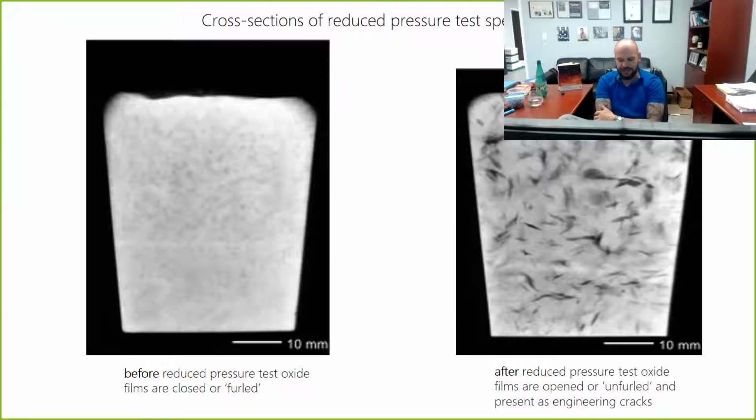So the casting is going to look like the little casting cup, metal solidifies, looks like a muffin top. We'll do a density evaluation, those kinds of things, and determine whether or not there's a problem present. So here's how we can prove bifilm theory. So here is 2 cups, 2 tests.